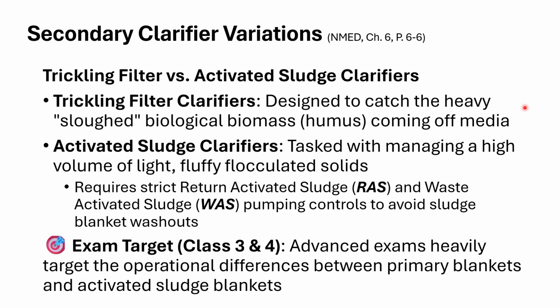We can have a trickling filter clarifier, and that's basically, if you think about it, filter media like rock that we allow the wastewater to flow over. And what happens is on that rock or that filter media, and the reason I call it rock is I want you to get the idea here that these are some rather large surfaces we want to deal with. It's not sand where we're trying to trap things.